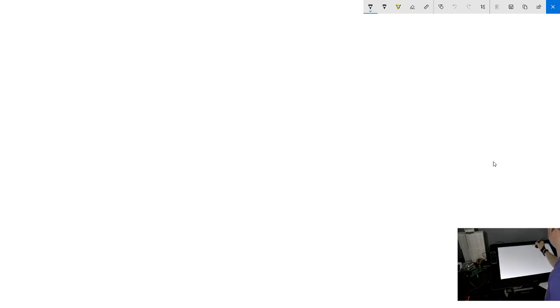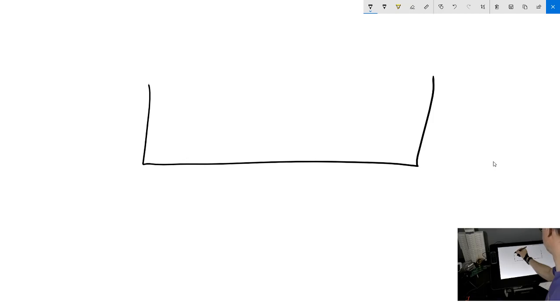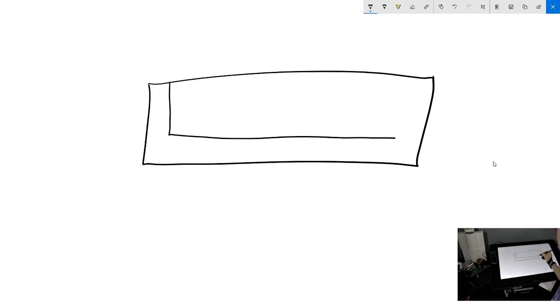And let's see. Okay, so here is a chip. And we're going to make an NPN transistor. So first we're going to lay down a bunch of N-doped material, and then we're going to lay down a bunch of P-doped material, and then we're going to lay down some more N-doped material. Now, this is extremely simplified. I'm not going to put in all the details about how you make a chip, but in essence, this is what it looks like.